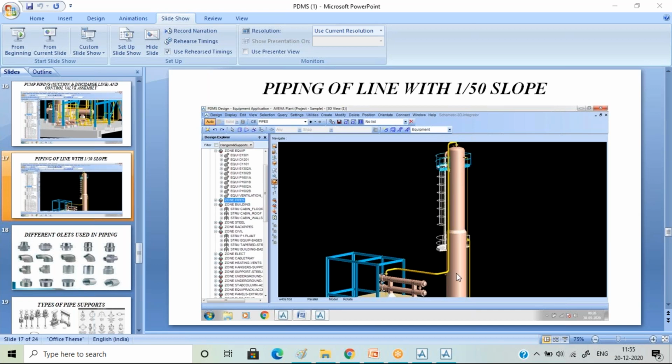You have to feel the growth of the line. That is what we say in piping. Basically in stress, we say that you have to feel the growth of the line. Now the growth of the line again will be explained by me, because my work is also stress. I also work on stress. So how will you realize the growth of this line? This section is fixed, this one is fixed, so these two joints are fixed.